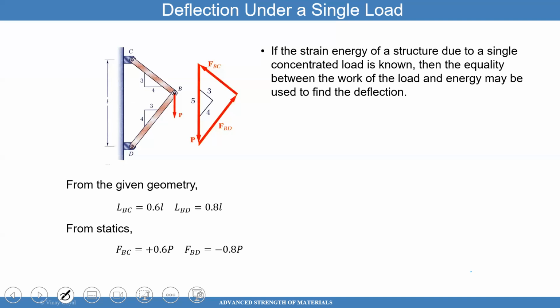So I really think that you want to be like these beams, these trusses here. A lot of positive energy. These are all positive energies, by the way. So when I apply a load P, this bar is going to stretch, you agree? And this bar is going to do something also. Even though it's going in compression, it's not negative energy, it's positive energy. So both of those bars will produce strain energy, 1 and 2.